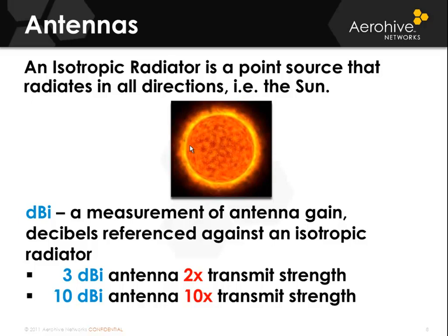Another way of phrasing this is decibel gain in reference to an isotropic radiator, or change in power relative to an antenna. Since antennas are measured in gain, not power, you can conclude that dBi is a relative measurement and not an absolute power measurement. dBi is simply a measurement of antenna gain.